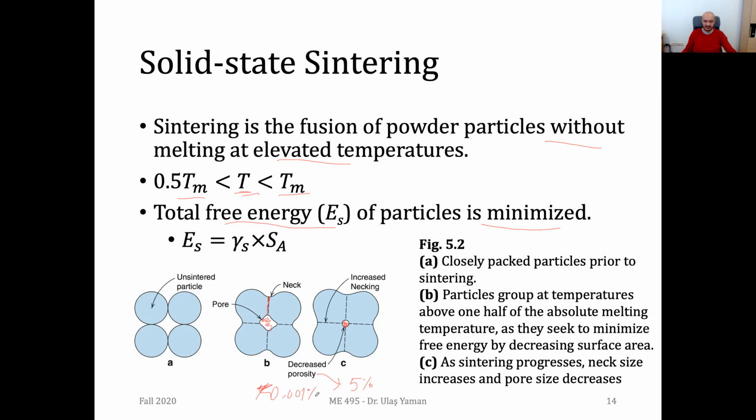Obviously, this should be on the right-hand side. Very low porosities. Since once you have porosity, then that means the strength of your part will be decreased. So that's why most of the companies are trying to adjust their parameters so that they will have a very low amount of porosity and the strength of their products is improved.